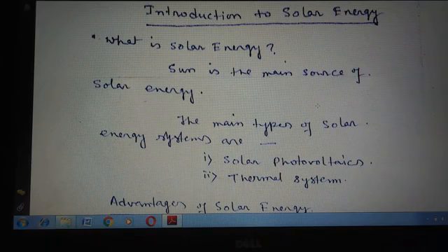Only the direct heat energy can be collected through a collector. The ratio of direct to total heat energy varies from place to place and depends on atmospheric conditions like dust, smoke, water vapor and other matter. The ratio varies between 0.64 and 0.88 according to different investigations.